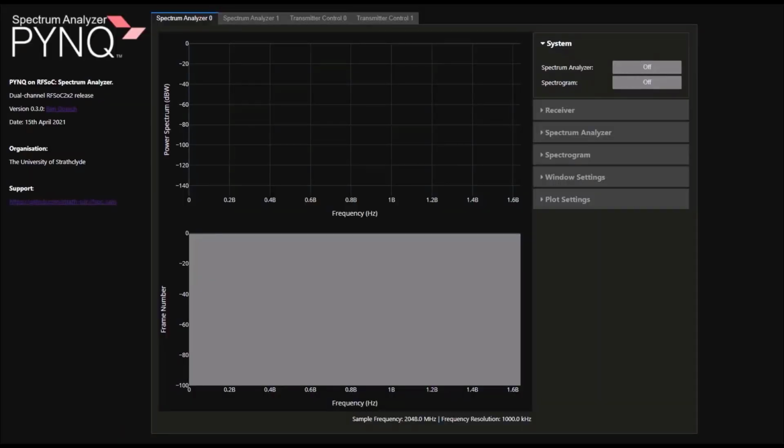In this video, we are going to briefly explore the second Nyquist zone of the RFADC samplers. The spectrum analyzer is capable of inspecting 4 GHz of spectrum. Its instantaneous bandwidth is up to 2 GHz. Therefore, we can only calibrate to one Nyquist zone at a time. In this example, we are going to calibrate the RFADCs such that they operate in the second Nyquist zone. This will allow us to inspect Wi-Fi signals at approximately 2.4 GHz.